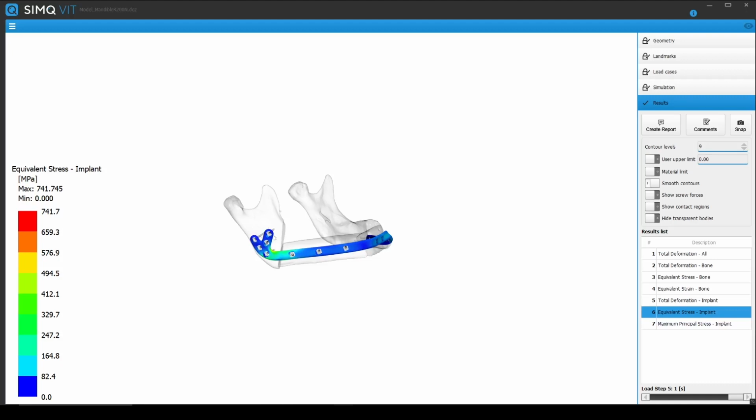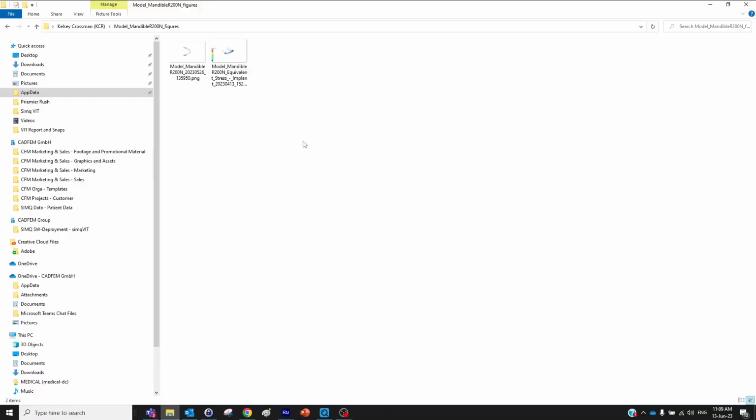Snap. Snap takes a screenshot of the window of the project. After clicking on the Snap button, it will appear as though nothing happens. However, this is not the case. Clicking this tab takes a screenshot from the current screen of the graphics window only, and automatically saves it to a new folder. No need to click multiple times.